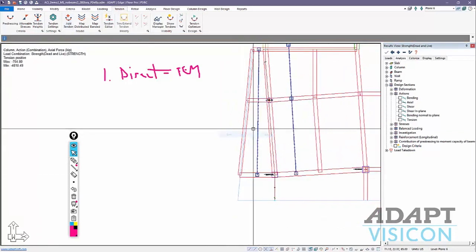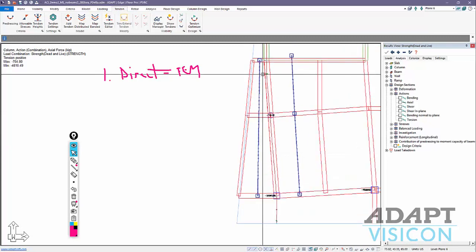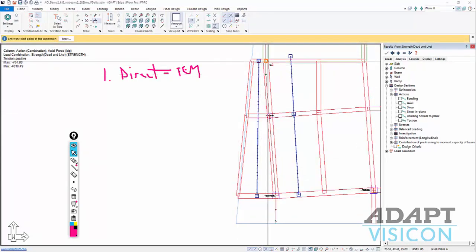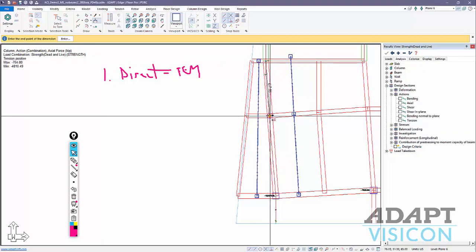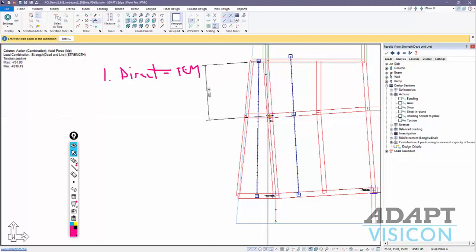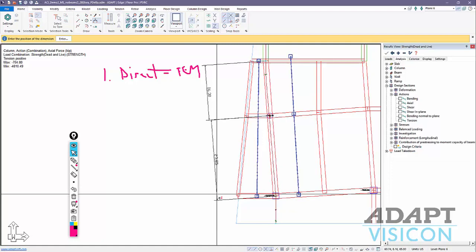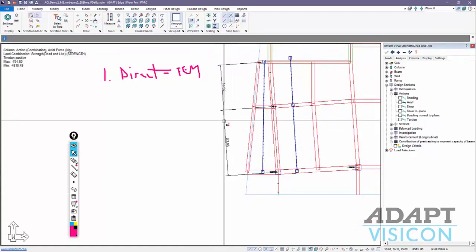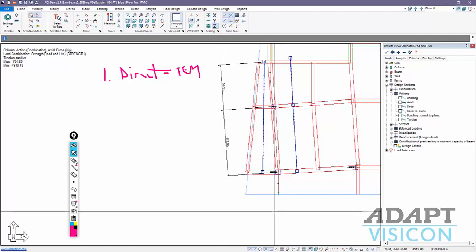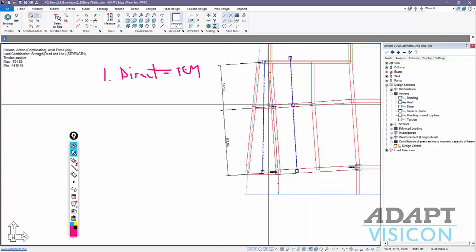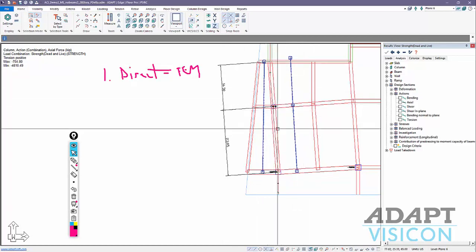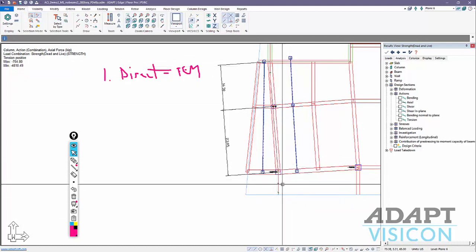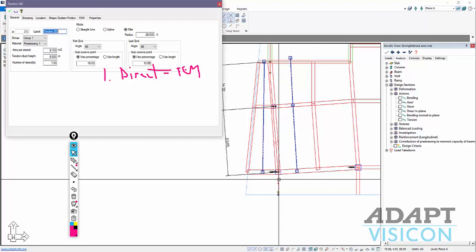So there's my cable, and if I dimension this, the tendon starts here at the top end, so I'm going to dimension from there to the point of the concentrated load, and also over to here. And if we take that ratio, this point load happens around 0.4 times the length of the tendon, or the length of the span.